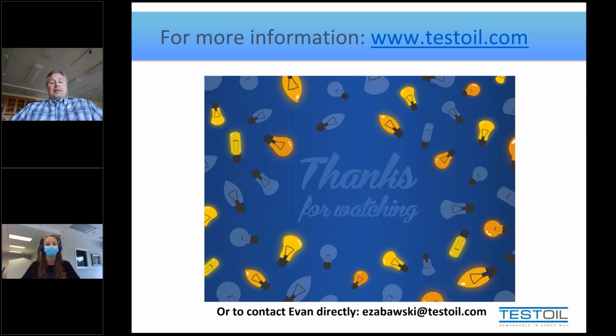So a report's not going to come with a pat statement that says, thou must change your oil today. We may put it as part of a recommendation saying, yes, maybe the acid number is so significantly high, maybe other degradation characteristics would suggest that replacing oil may be one of the only options. But if you truly want an answer to that question, then it's best to phone us and talk to us directly and help us walk you through interpretation of the results, where we can share information back and forth to help decide if that really is the only course of action.